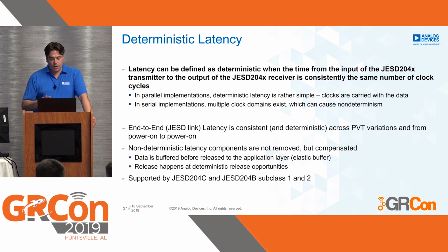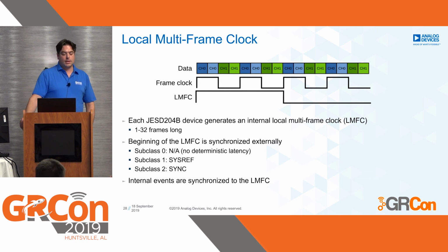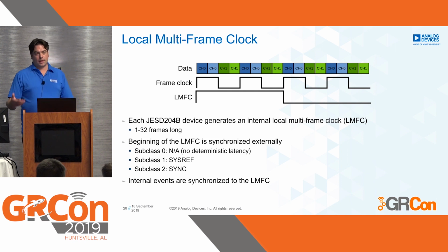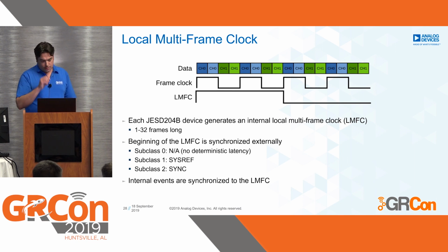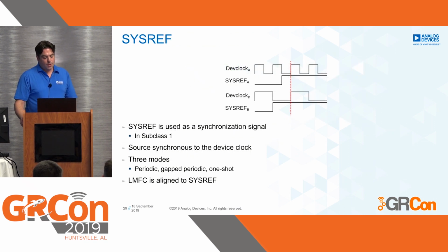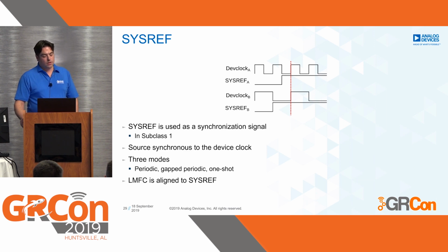There are different subclasses. In subclass 0, there is no deterministic latency. In subclass 1, it's using SysRef to achieve that. What SysRef basically does is align the local multi-frame clock, a clock that's running in the link layer of the JESD stack. This SysRef pulse is synchronizing this clock across multiple devices. I mentioned it before, SysRef is the pulse that does it, and SysRef is source synchronous to the device clock.